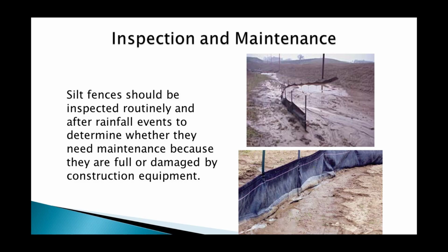Inspection and maintenance is required after every major rainfall event. They should be inspected routinely and after rainfall events to determine whether they need maintenance because they are full or damaged by construction equipment. In the upper right-hand picture, you can see where the silt fence has not been maintained, that it needs to be removed and replaced, or the sediment has to be pulled out.